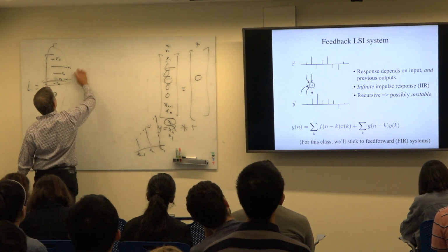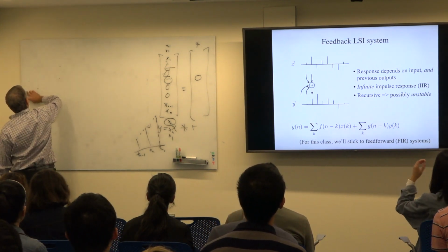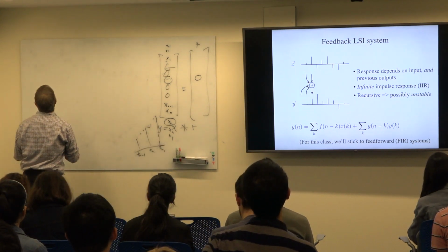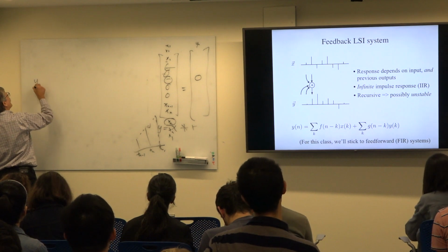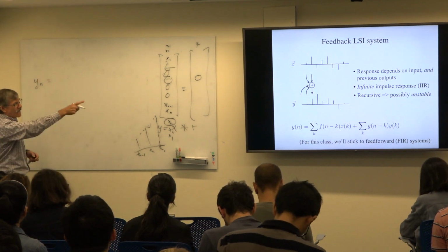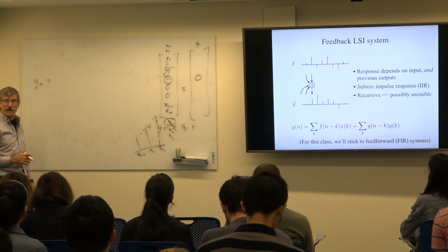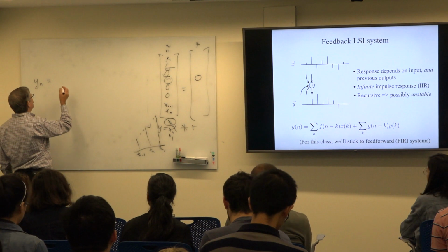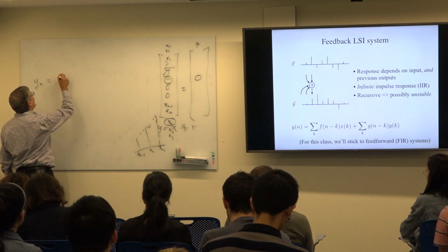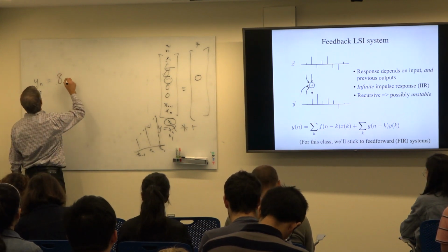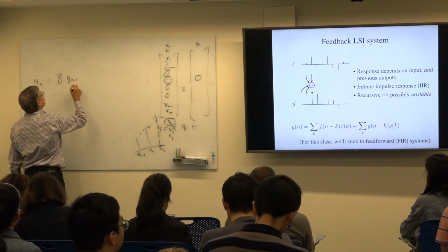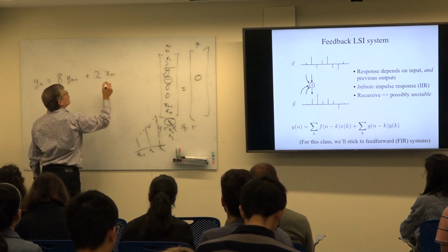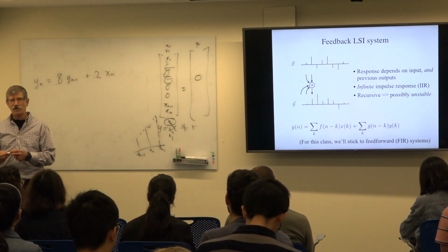And so I'm going to give you the simplest of all possible examples. Suppose I say that the output at time n is going to be a weighted sum, as written there, of various inputs and various outputs. I'm going to make it really simple, and actually use real numbers too. I'm going to take 0.8 times what the output was the previous time step, plus 0.2 times the input now. Those numbers are 0.8 and 0.2.